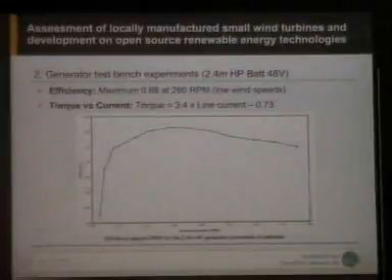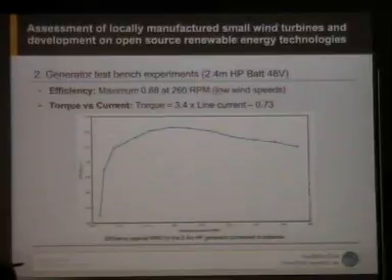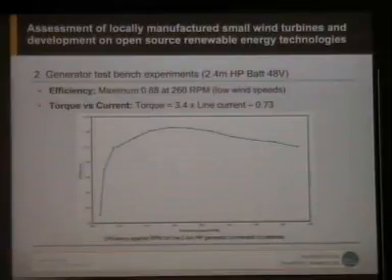This is the efficiency of the same generator, so it's efficiency against rotational speed. We see that we are operating at efficiencies close to 85%, and then going down to 80% at RPM that is close to lower wind speeds. Okay, the efficiency is basically what is coming out of the generator. Related to calculated power, is that your...